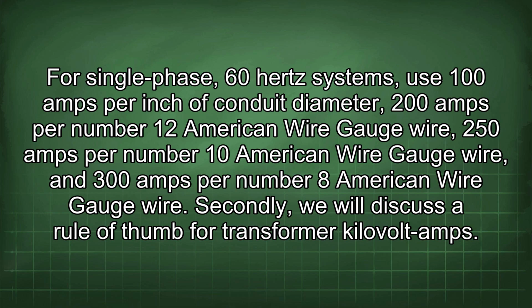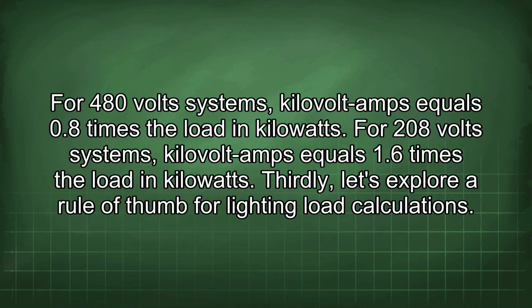Secondly, we will discuss a rule of thumb for transformer kilovolt amps. For 480 volt systems, kilovolt amps equals 0.8 times the load in kilowatts. For 208 volt systems, kilovolt amps equals 1.6 times the load in kilowatts.